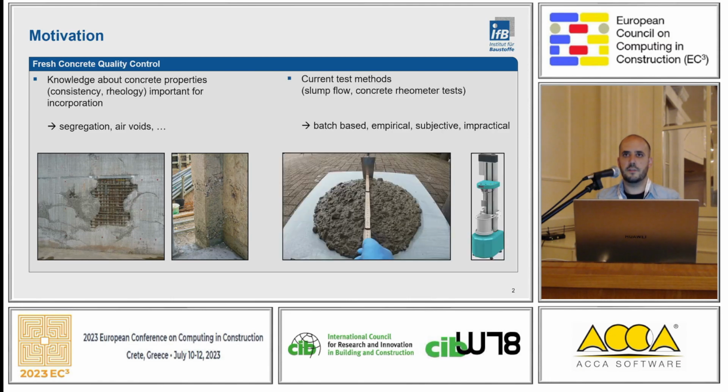So current test methods are, for example, the slump flow test, in which the concrete is spread on a standardized table and the diameter is correlated to the consistency class, or rheometer tests, which are more like laboratory tests and not so much practiced on the construction site. And both of these test methods are batch-based, empirical, sometimes even subjective, and as I said, impractical on the construction site.